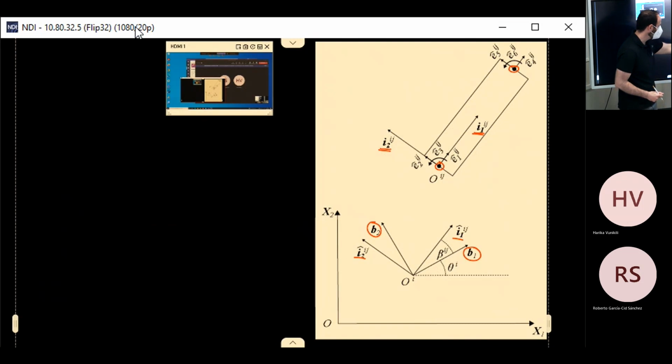The intermediate frame forms an angle beta_ij, which is constant because eventually these two frames are parallel, but then these will deform and move, and these instead will retain their orientation constant with respect to the body frame. And then the body frame has the typical angle theta with respect to the inertial frame. This is the theta that is inside the rotation matrix that we know.